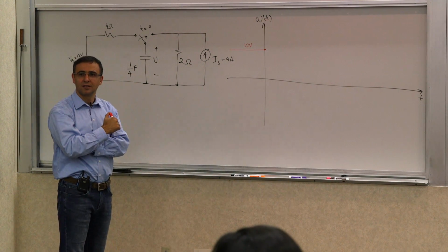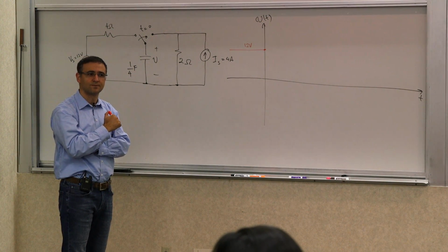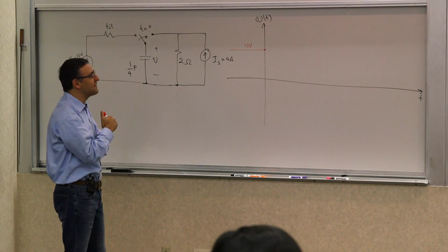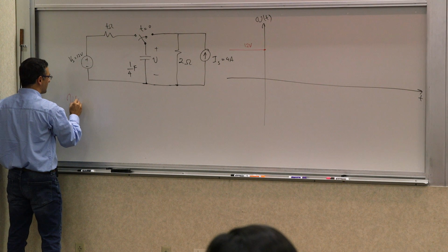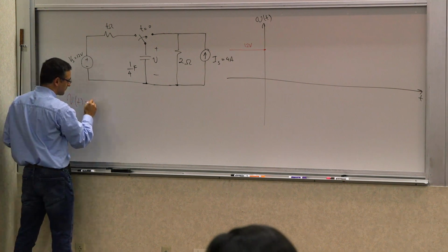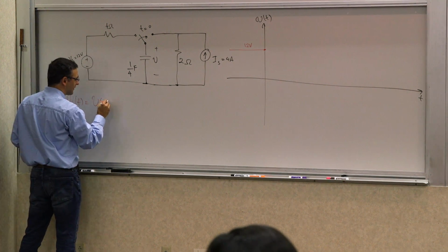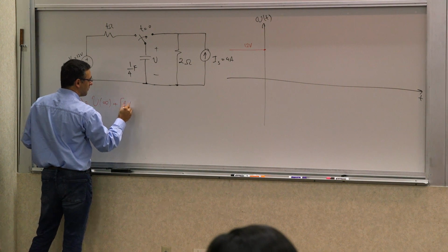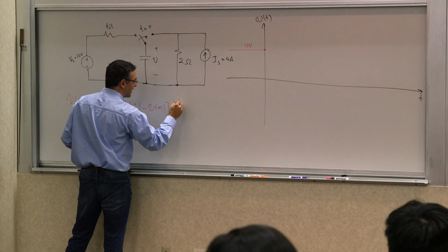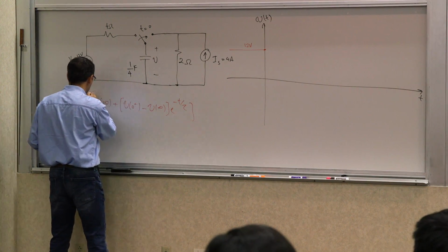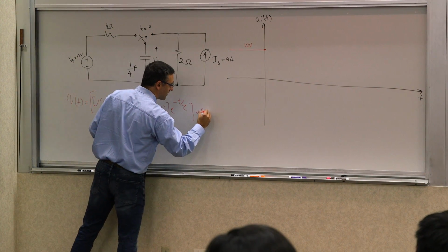That expression that we just developed. So V of t is going to be V infinity plus V0 plus minus V infinity times e to the negative t over tau, times u of t. And don't forget these u of t's, because you will see they are important.